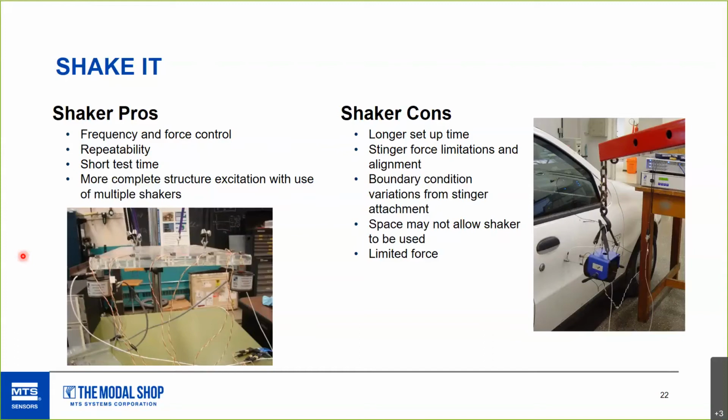Let's say you had a temperature varying object or environment. Having a bunch of accelerometers and testing with as many shakers as are required to excite your structure fully lets you get all your data quick. So all of your time concerns can usually go out the window with a shaker. But if funds are tight, accelerometers usually are used in greater supply, larger quantities for a shaker test.